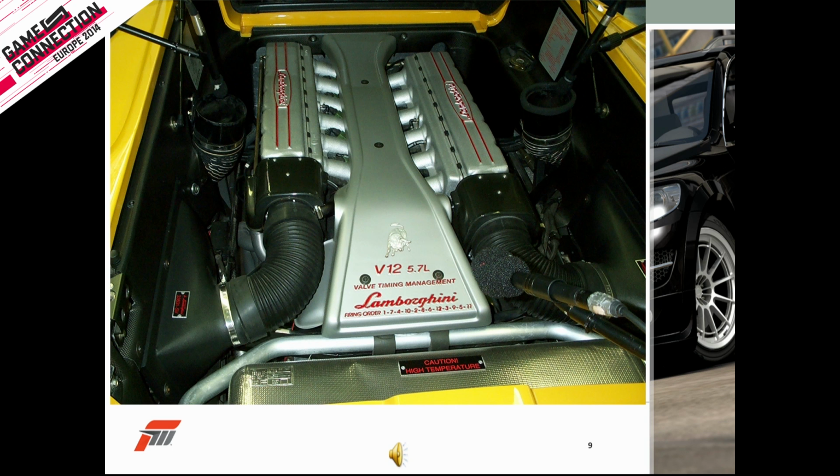Air comes in here. You can see we have a mic on it. We have a DPA mic, close micing it. Air comes in here, goes through the air filter here, goes here to the throttle body, which is controlled by your gas pedal. It's kind of ironically named, because the gas pedal is actually the air pedal. As soon as you step on the gas pedal, this thing opens up and lets air into the engine where it gets mixed with fuel. And then these here are the exhaust ports. So air comes in here, gets blown up, and then gets shot out these exhaust ports, which make their way on out through the exhaust system and exit the pipe.